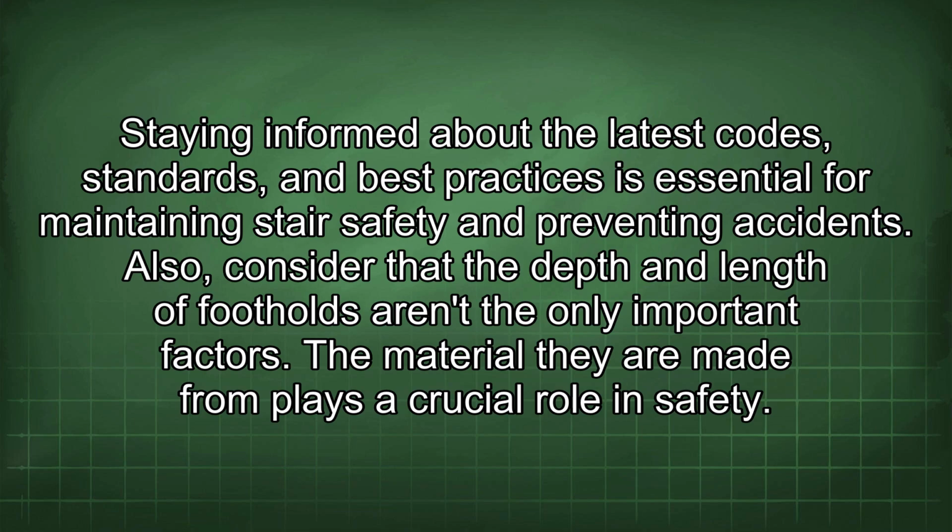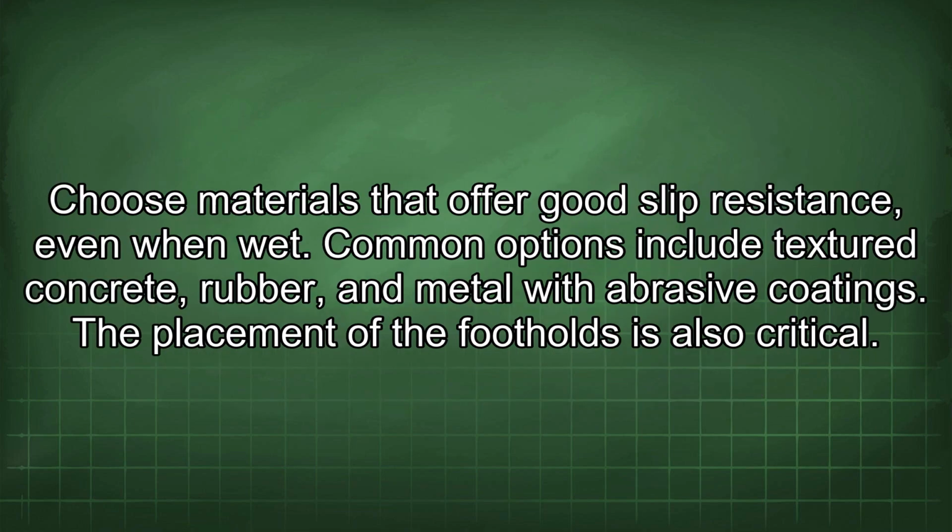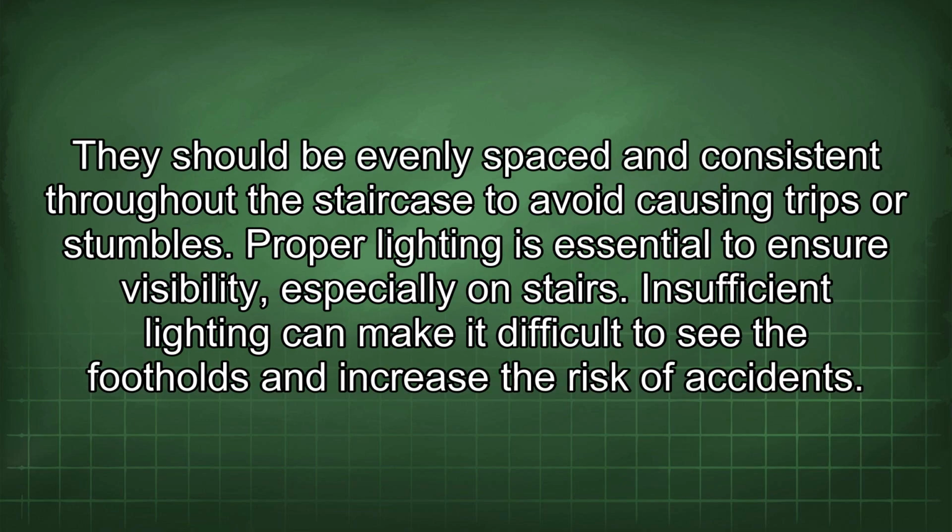Also, consider that the depth and length of footholds aren't the only important factors. The material they are made from plays a crucial role in safety. Choose materials that offer good slip resistance even when wet. Common options include textured concrete, rubber, and metal with abrasive coatings. The placement of the footholds is also critical. They should be evenly spaced and consistent throughout the staircase to avoid causing trips or stumbles.